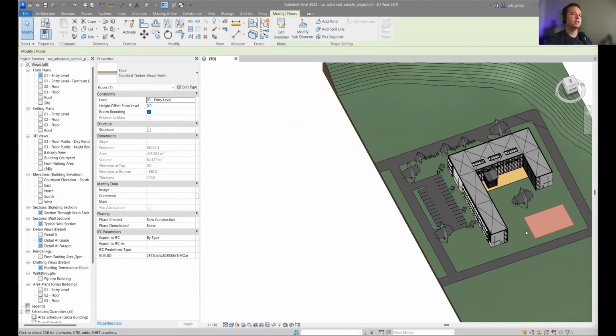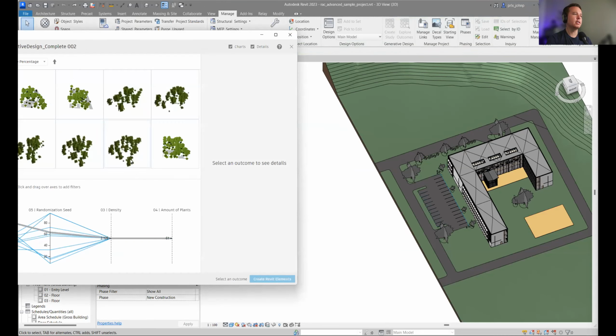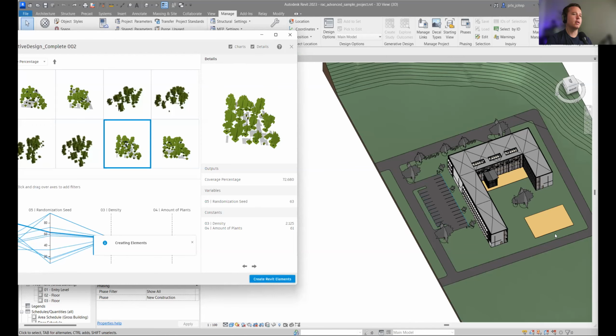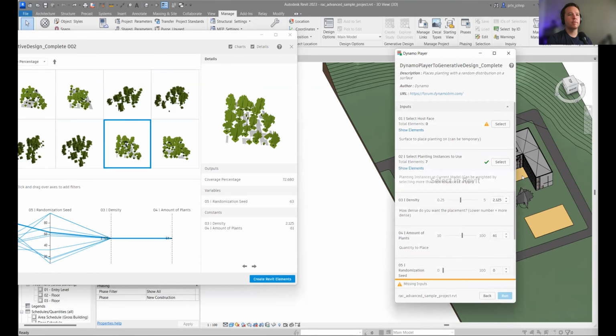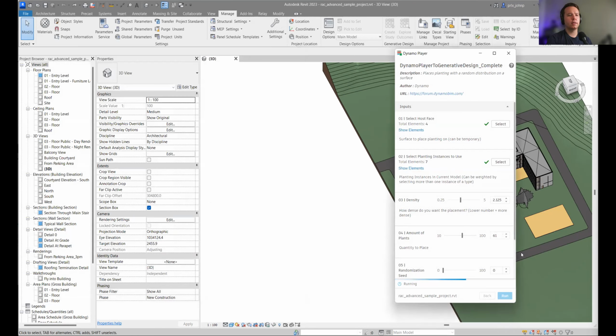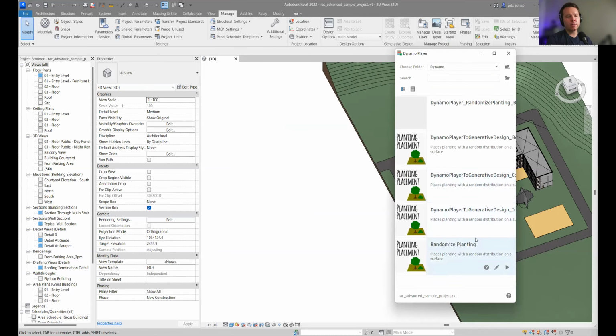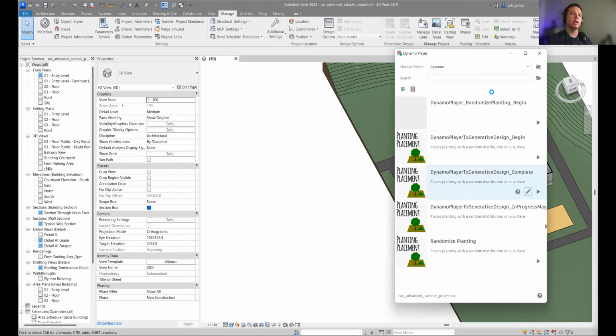Yeah, something changed with my point placement, so that kind of stinks. That's always fun. Because it does work in Dynamo Player, so that's a bummer. If I were to select the surface and run it, it was working earlier. Oh, the gate's closed in Dynamo Player, so that's not going to work either. Fun times. So that's the one thing: that gate you will have to make sure you open and close depending on what you're debugging.